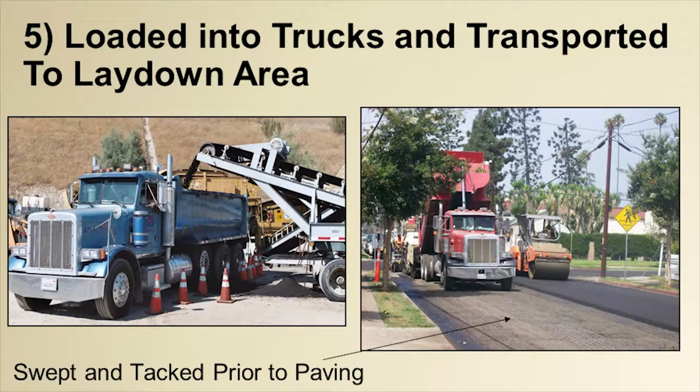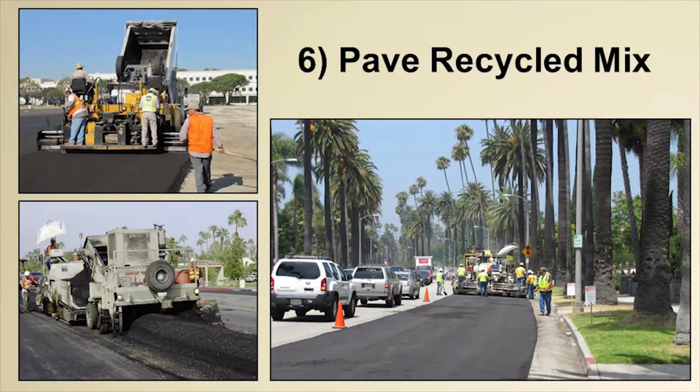I'm going to give you just a couple of construction things. You should sweep and tack it before you lay it down, just like you would an HMA. We pave it. You can see the density of the roads that we have over in here. We do it in traffic all the time. Again, just a couple hours. Then release that lane.